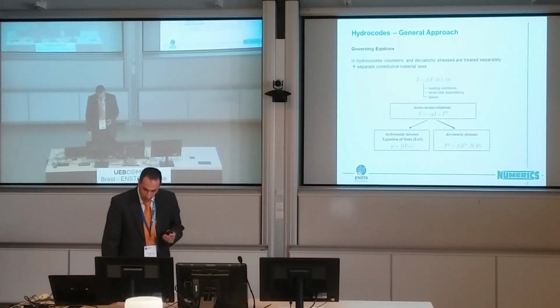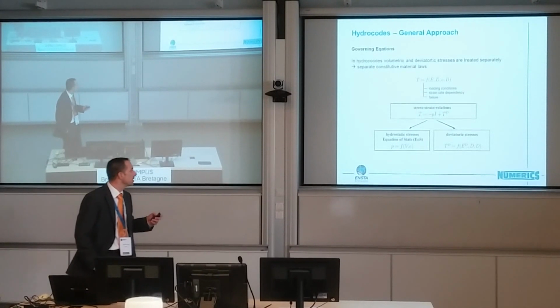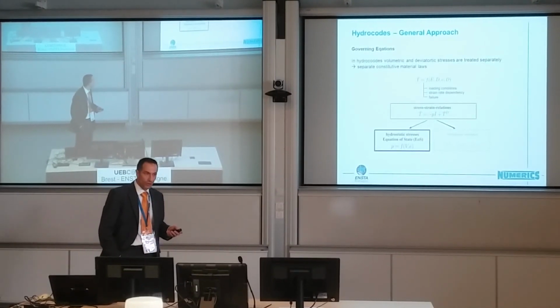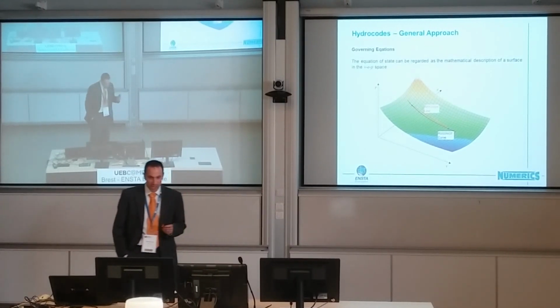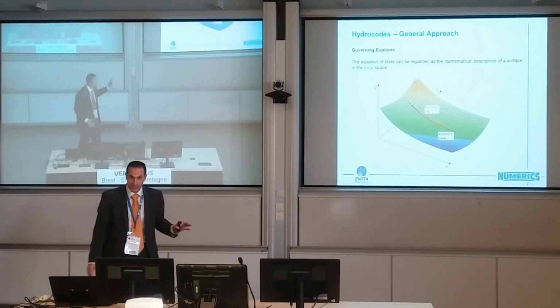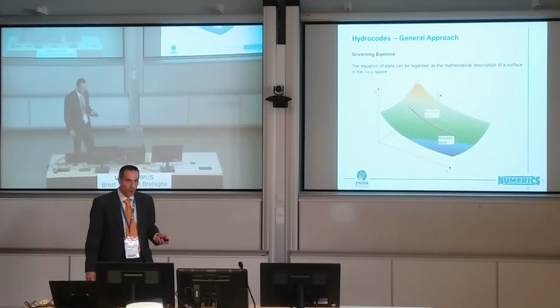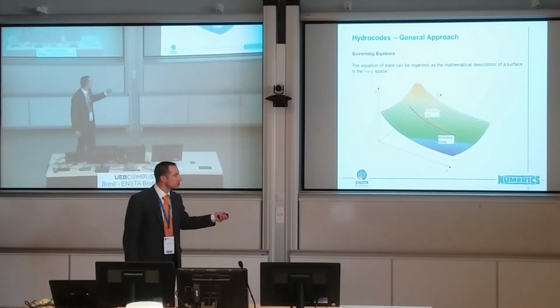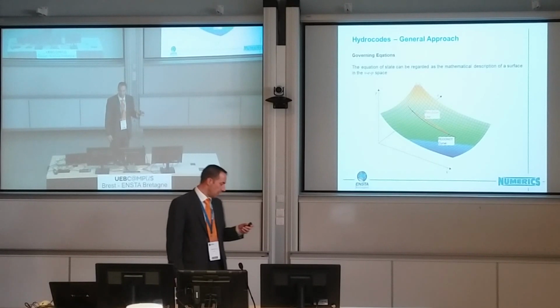But for our explosives, we do not regard strength at this moment, so we will concentrate on the equation of state. The equation of state is actually some kind of surface in the PVE space, pressure, energy, specific volume, and it describes all states the material can take.